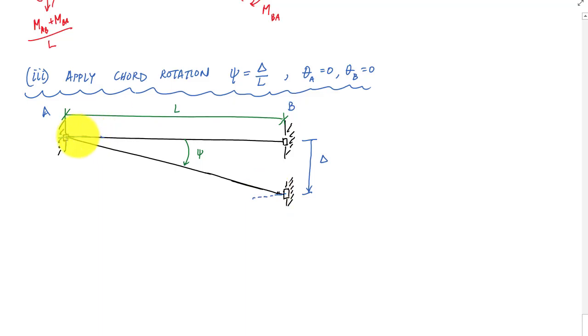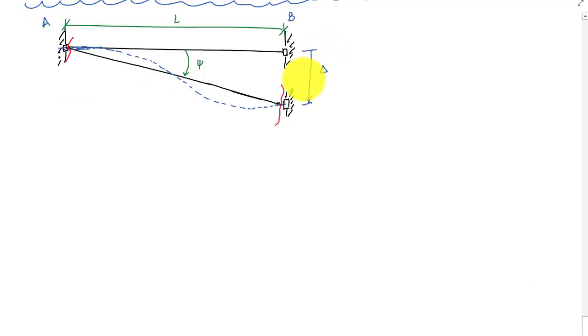And so my beam, the blue line, would show an exaggerated deformed shape of the beam, and it would look like this. And if I cut it out, again, this is the exaggerated deformed shape. This delta, this settlement, is exaggerated as well. But in this deformed geometry right here, I would have the end moments associated with this dotted blue line. If I look, end AB is concave down.